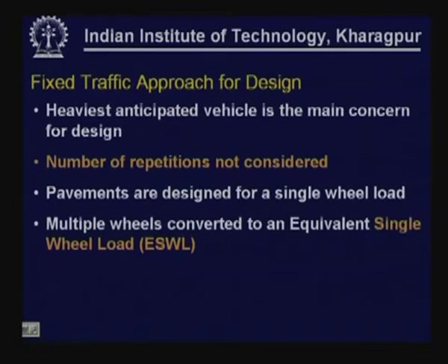In the fixed traffic approach, the heaviest anticipated vehicle is of importance for us. This is our main concern. The number of repetitions that a given facility gets is not of that much significance compared to the load that the heaviest vehicle is going to carry. We are very seriously concerned about the load that the biggest or heaviest vehicle is going to apply on the pavement. Naturally, these are facilities where the number of repetitions is not that